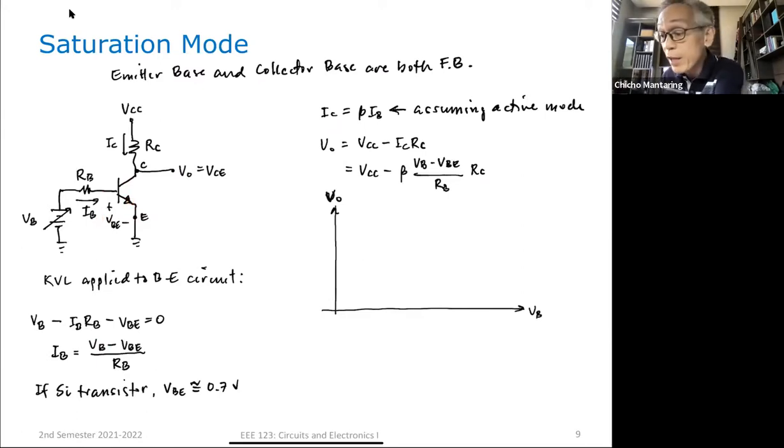What does it take for a diode to start conducting? What will it take for this diode to start conducting? How many volts should the open circuit voltage across it be? I'm just trying to wake you guys up. Anyone? Okay. For this diode to start conducting, the open circuit voltage across it has to be greater than or equal to 0.7.